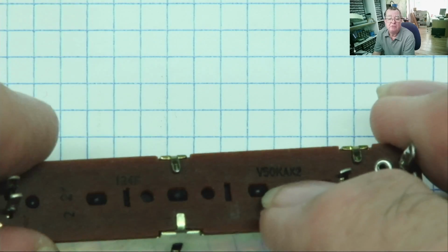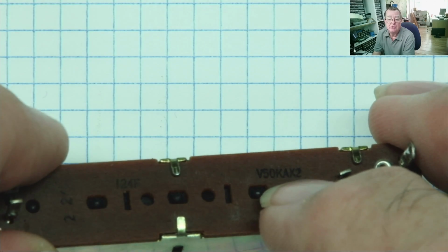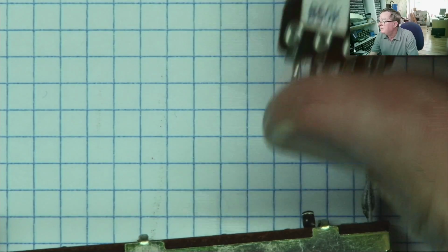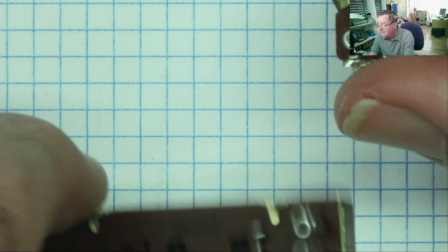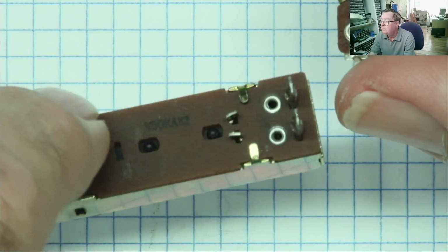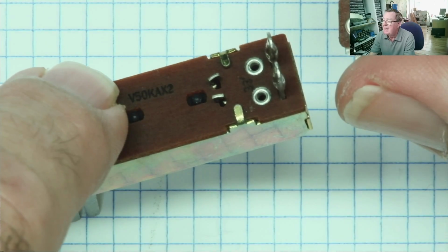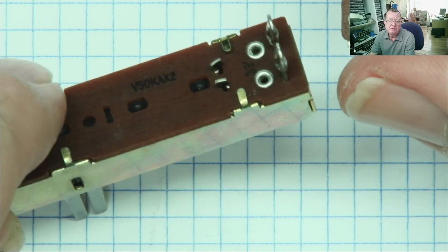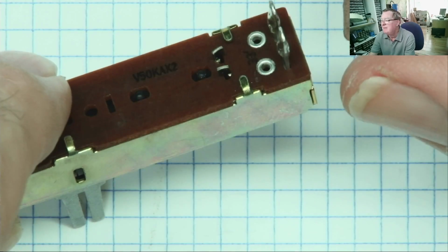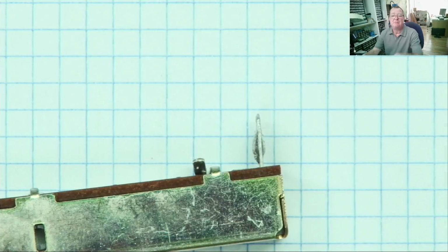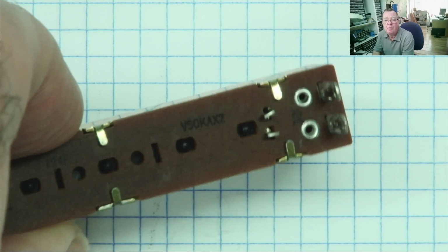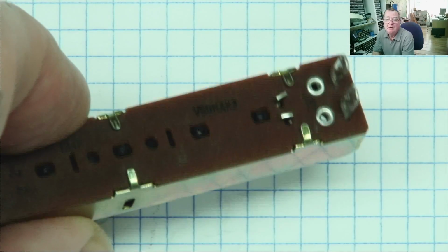So if you want a linear potentiometer, I'll show you one. This is a linear one. You see this says B50K. So we get A and B. The way I remember it, I always think A for audio, and audio uses logarithmic scales. That's the way I remember it. There's probably some better way, some better mnemonic. Guys, comments below. Anyway, that's the answer to that one. And if you got it wrong, well, I'm sure you've actually learned something now. So it was still good.